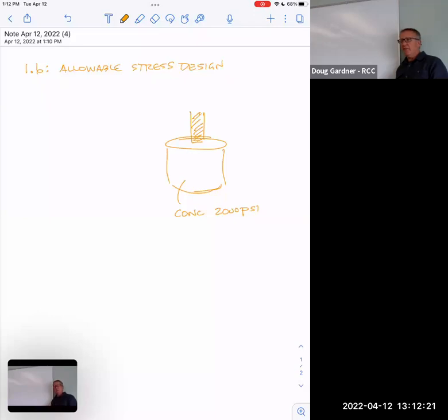So obviously, for a bridge or something you want to last a long time, and if it breaks, people die. This is something like a sidewalk. I don't know, if it cracks, who cares? So sidewalks and driveways and stuff are usually 2,000 PSI concrete, but they'll bump it up. Well, does it make sense that's the allowable stress? You better not put more than 2,000 PSI on that, or it's going to break. So that's kind of the sigma number, right? That's kind of the idea in this section. You already know the sigma because you poured the concrete. Well, then let's work backwards and not put too much force on it.